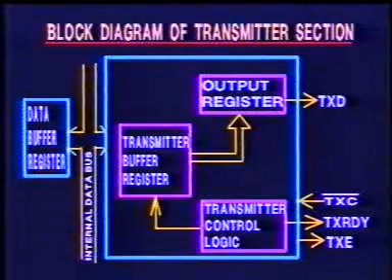The TX ready is raised after each data transfer from buffer register into output register. The TX ready may be used to interrupt the CPU for a new character. Framing bits are added. The assembled character is sent out through TXD bit by bit.